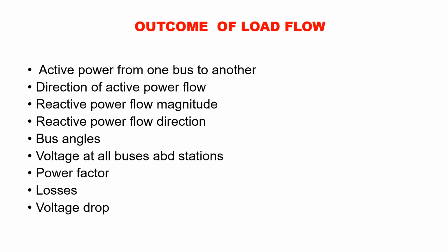And one very famous thing I have been talking about, the bus angle, you also get from the load flow study. So load flow study is basically done to check whether the system is stable or not in a steady state condition when there is no fault. That is, you assume the outage of a line, you disconnect a line, disconnect a generator, but you do not create a fault.